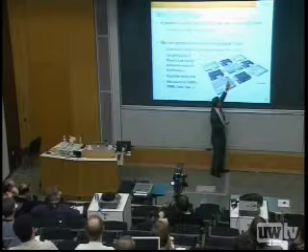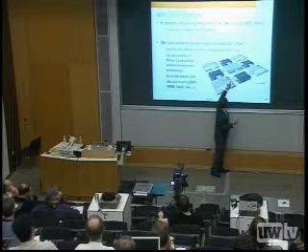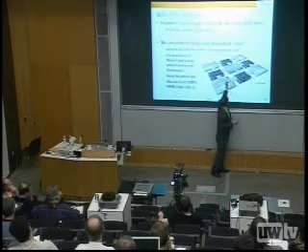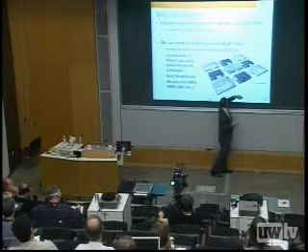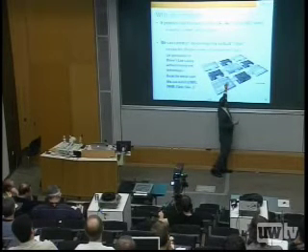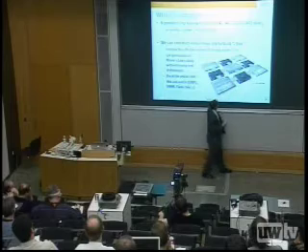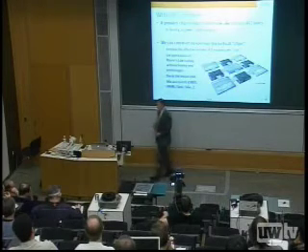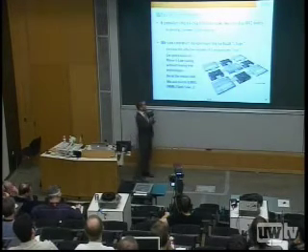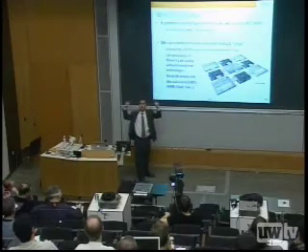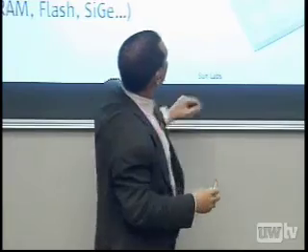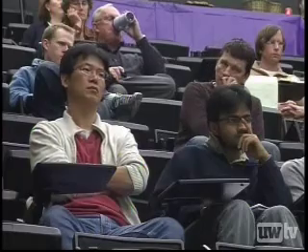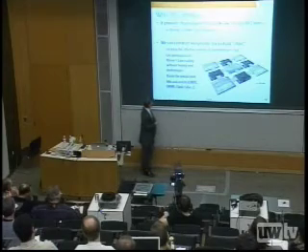What's a bridge chip? A bridge chip is a chip that has proximity I/O on its edges and wires, on-chip wires that run across them. So I can get from this processor to this memory stack through this bridge chip, which has interconnections that are very inexpensive, just like they were on-chip wires, which really means I've made a virtual chip. I made a virtual chip out of many, many small chips, or even medium or large chips, and such that I can sort of fake generations of Moore's law scaling and mock up this large silicon system.